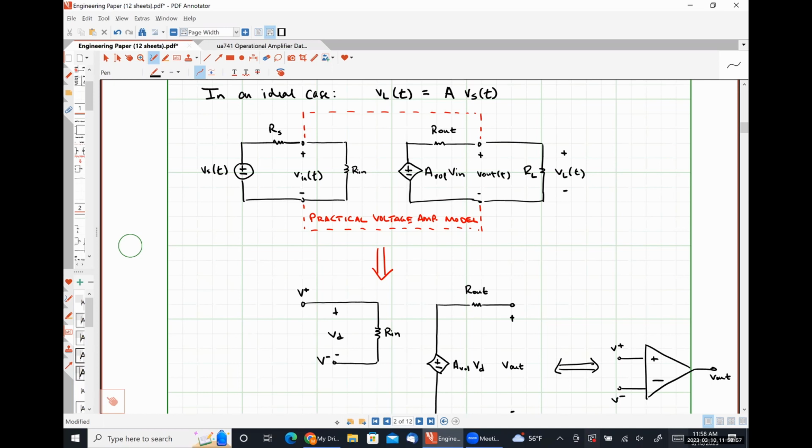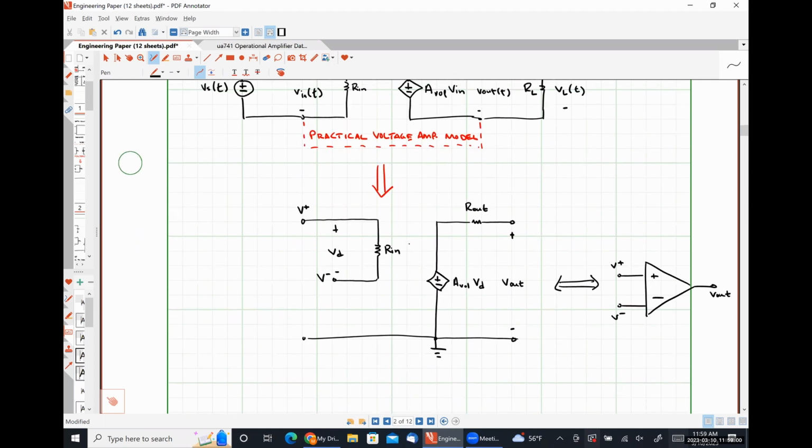Our output voltage is measured with respect to that purely because I said it is, right? No, and I mean that literally. If we were to wire up a circuit and we didn't put our load resistance between here and ground, the number would change. If I threw another resistor here and then said my output voltage is this thing, that might be different depending on what the value of that resistor is. We're just establishing a simple baseline with ground as a common reference point, because that's literally the job of ground, to be a common reference point.